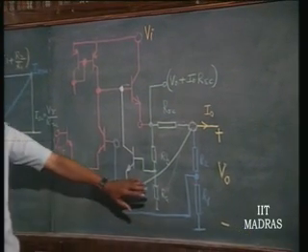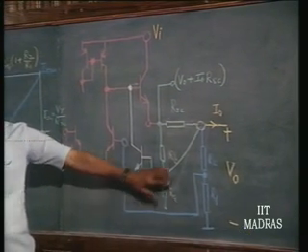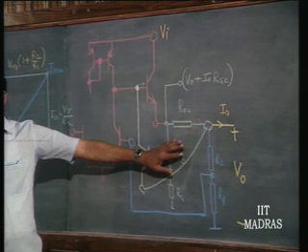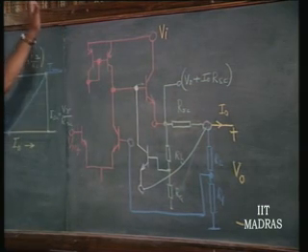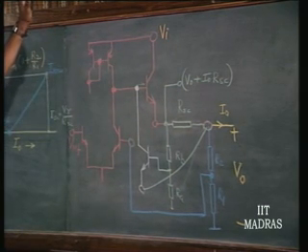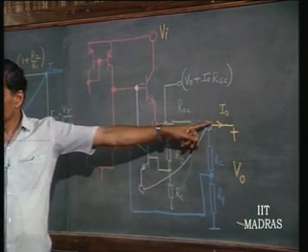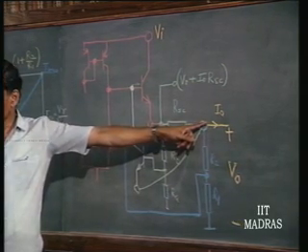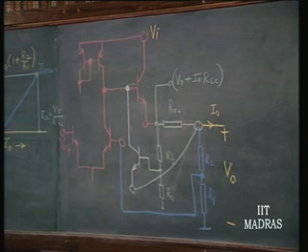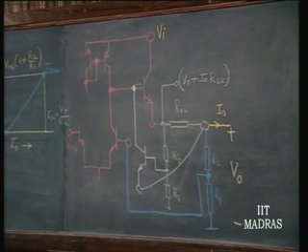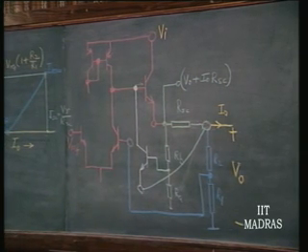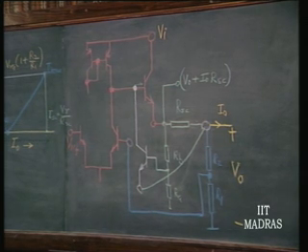If you make alpha equal to 1, it will be our old scheme. This will be automatically connected to that. The only thing we have now done is sense a voltage which is dependent upon the output voltage as well as output current, by introducing an attenuator.